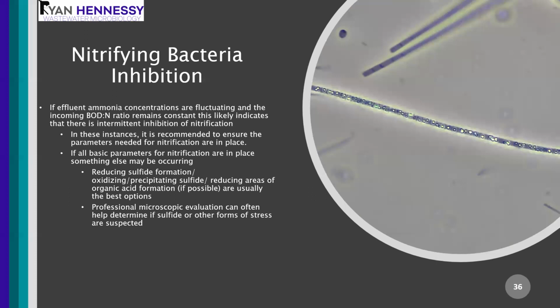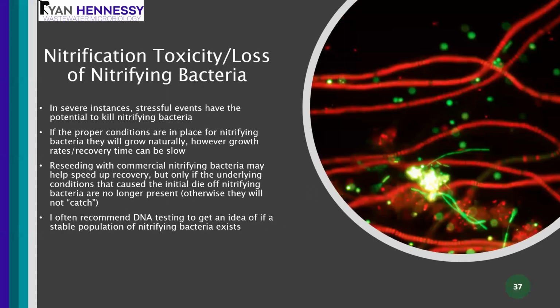So septicity, and also, before nitrification can happen, you have to have most of your BOD gone, and the bacteria entering that starvation state, or that endogenous state. Once the BOD removal happens, then the nitrification happens after.